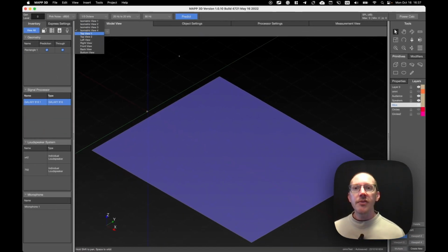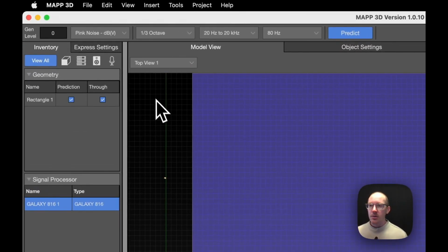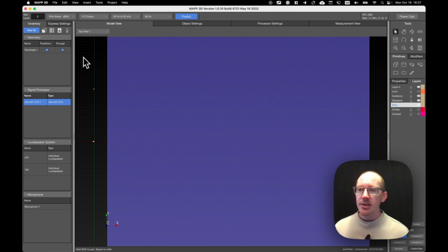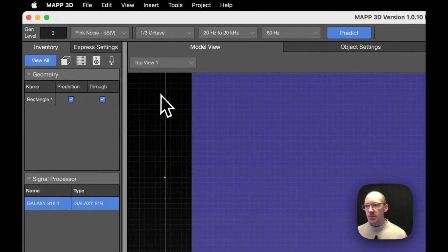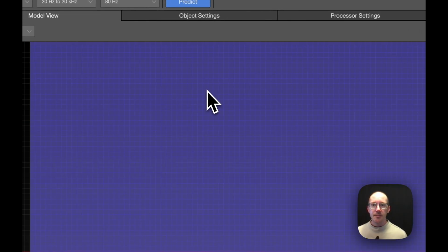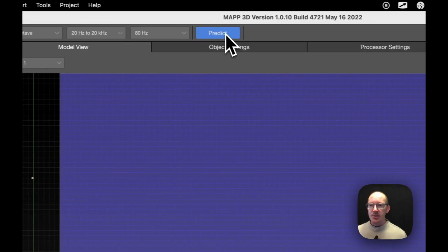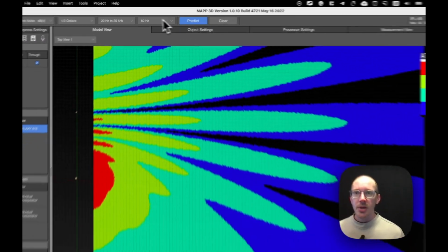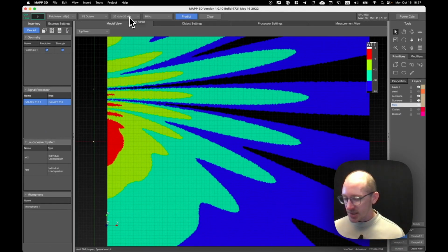Just out of curiosity, what if I told you nothing? What would you expect here? Let's say that Meyer Sound does not publish any kind of preset guide. They have their own solution of loading presets for handling this, but what if you didn't know anything, I didn't tell you anything? What would you expect here? Let's just make sure I have all these delay values cleared out. And let's do a quick prediction here. By the way, we're looking at 80 Hertz. I don't think I mentioned that before.